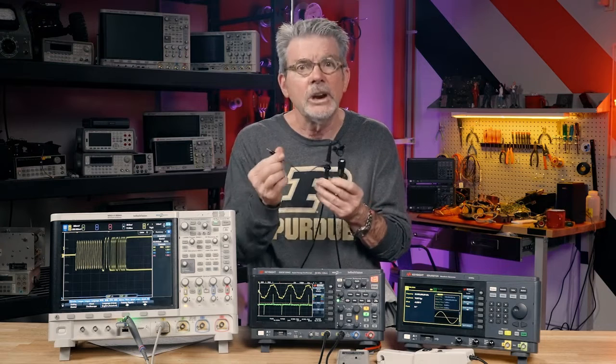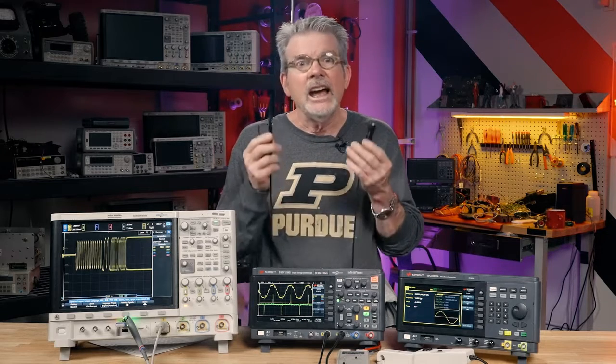Passive probes have limited bandwidth. About 700 megahertz is the tops you're going to get out of the standard passive probe. Passive probes can only measure voltage. They can't directly measure current. Passive probes can only make measurements relative to ground. They can't directly measure differential voltages. And the standard 10-to-1 passive probes have limited voltage range. They can't measure thousands of volts. You'd blow one of these things up if you connected it to very high voltage. Let's now look at some of our alternatives for these cases.